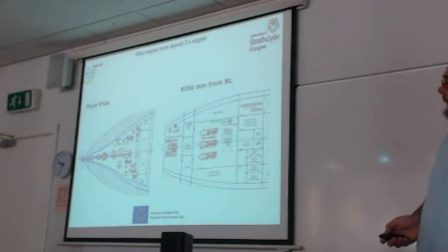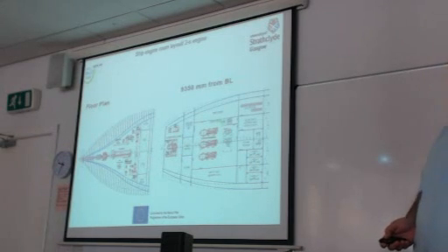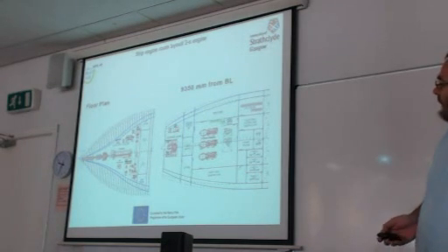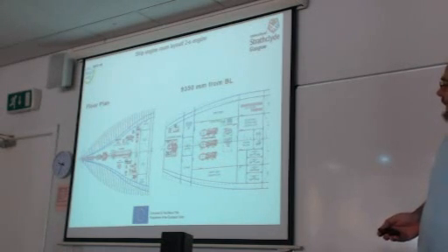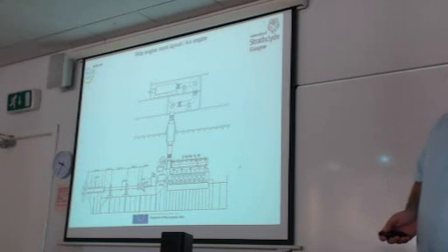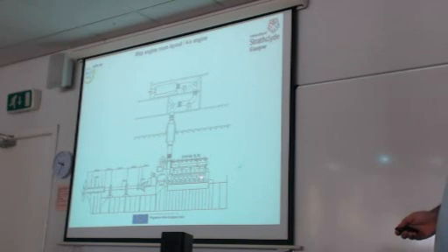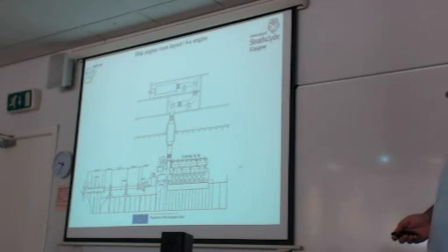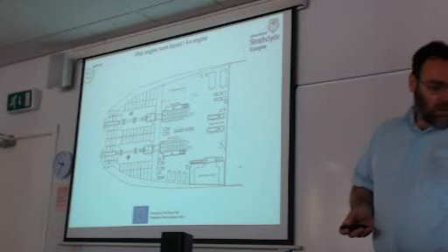These are some more views of the floor plan and the first deck plan of the same ship. So we have the engine shafting system. In this case, we have a shaft generator installed between the engine and the propeller. And then in the first deck, usually the typical installation is 3 diesel generator sets and medium speed or high-speed engines. And this is the case with a four-stroke medium-speed engine, a clutch and gearbox usually, shafting system and propeller.